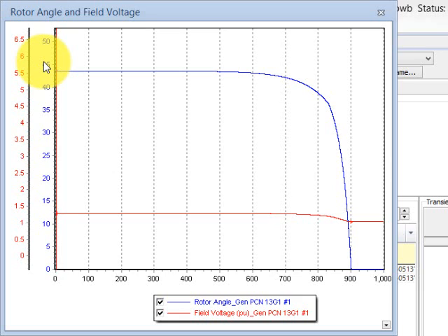So this error, let's call it an error. I doubt if they really have a negative droop on their governor, but this could persist in a model for a long time because you're not going to see it. Somehow we found it, and I don't think we were looking for trouble, but sometimes these slowly unstable modes can manifest themselves in other ways.